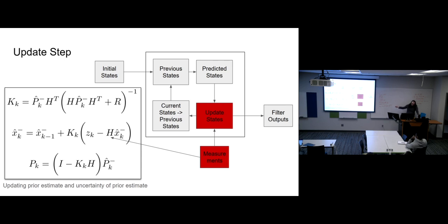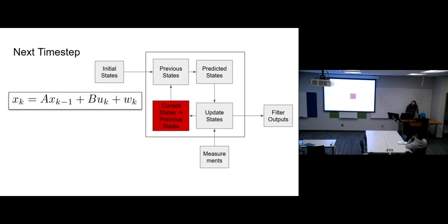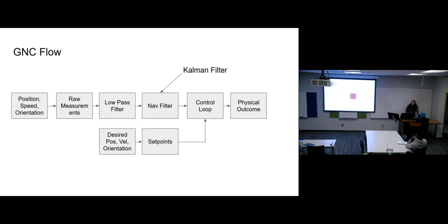So this top line here, this K of k, is called your Kalman gain. This is basically weighting your measurements with your probabilities and all your noise and saying, okay, what's my actual weight based on how I defined my model. Then you're updating all of this with your Kalman gain, and this H is your measurement, so you're pulling that back through here. And finally, down here you're getting the uncertainty, updating everything. And then you basically tie it back through, and that's at a high level.